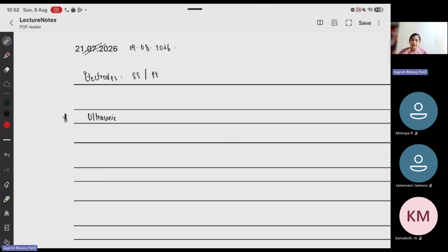So you use a high frequency sound wave, and the difference in the frequencies that occurs when you're trying to measure it is what tells you about the Doppler shift, the shift frequency, and that shift frequency tells you about the blood flow velocity, right? So you use sound waves, you use an ultrasonic sensor, and that principle is based on Doppler, right?